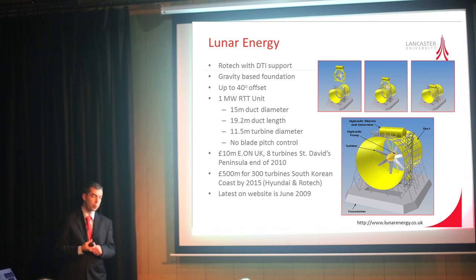People often ask about shrouded turbines, knowing this relationship in terms of the water velocity flow rate. If you can increase the velocity, potentially you get significantly higher power capture.